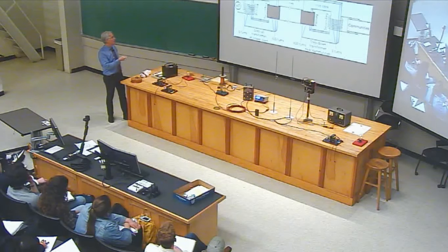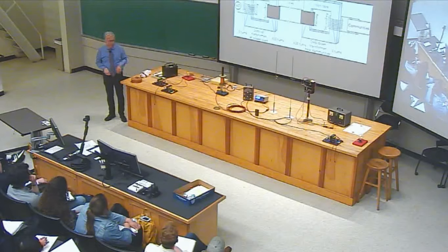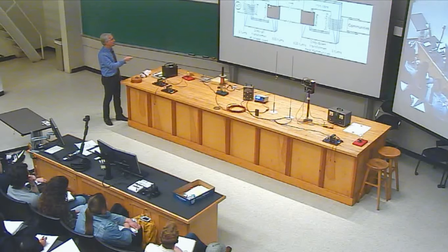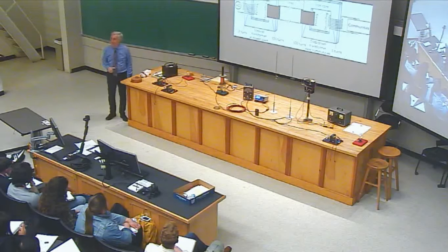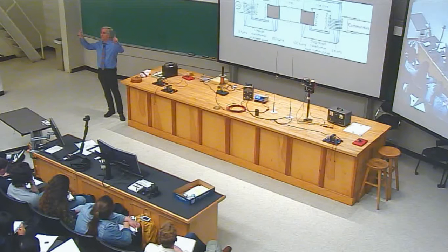The charges will not go from one circuit to the other, but we will take power from one circuit and convey it to a second circuit at much higher voltage, somewhere in the hundreds of volts, the way we've got it rigged up here. And so the power will now be moving in the second circuit, a circuit that lives only between a pair of transformers and has no other access to the outside world. This circuit will be a high voltage circuit, a couple hundred volts, with a small current running through it. You only need a small current to convey power when the voltage difference is big.